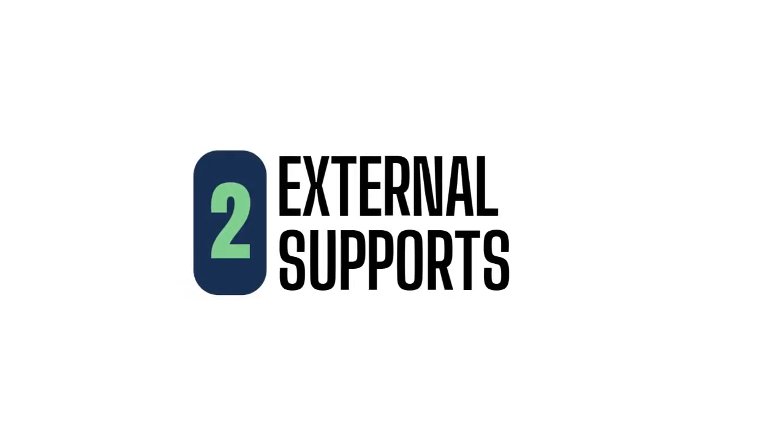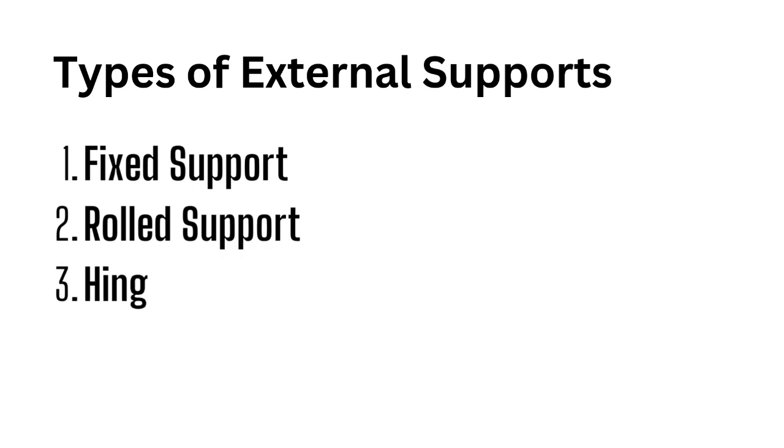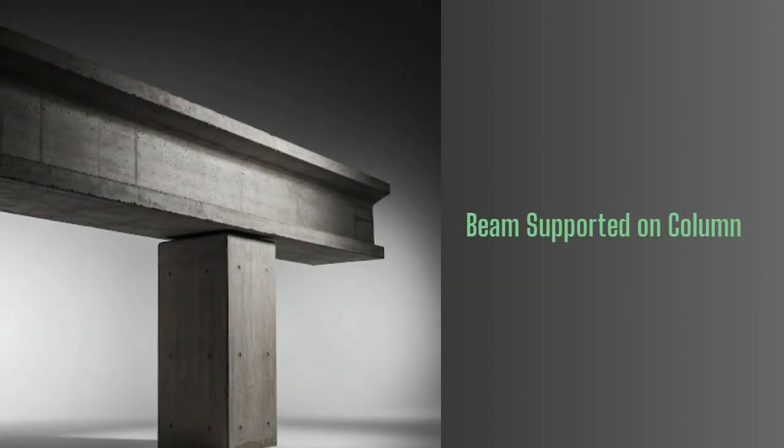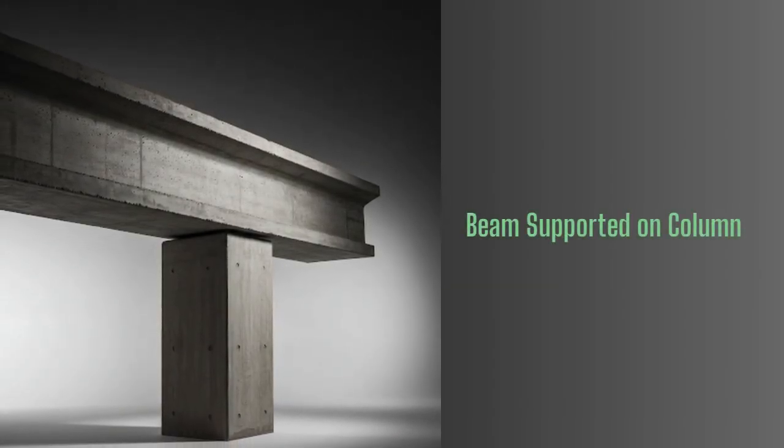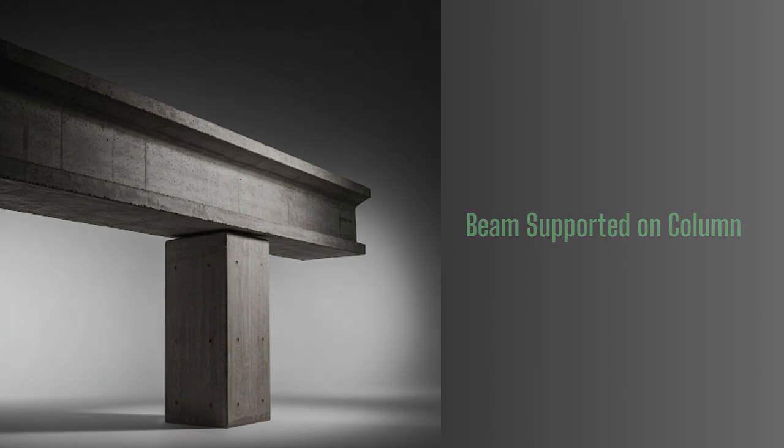Let's first discuss external supports. The various types of support we will study here are 1. Fixed support. 2. Roller support. 3. Hinge support. To explain these types, let us consider a beam supported on a column. Here the support is a column. How is the member supported on the column? Some sort of connection exists between the column and beam. Let's apply all possible supports and check what is the difference.